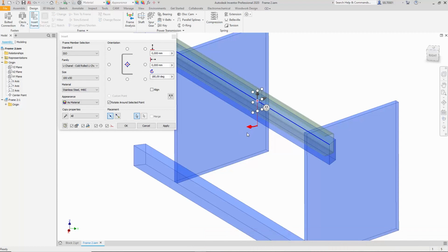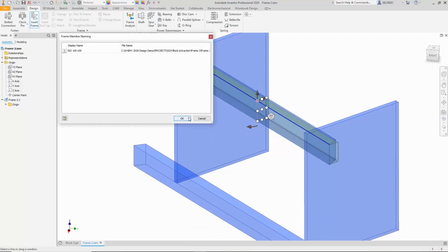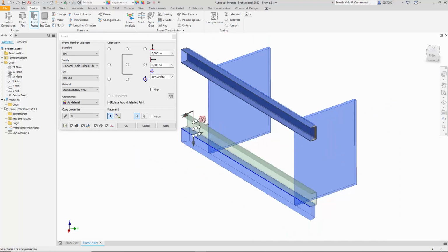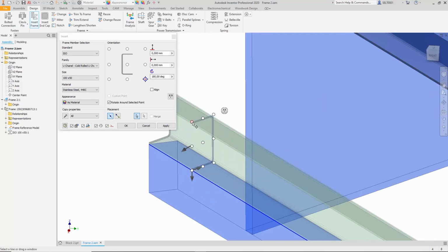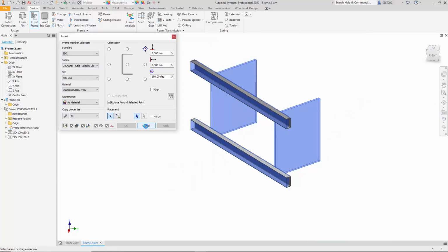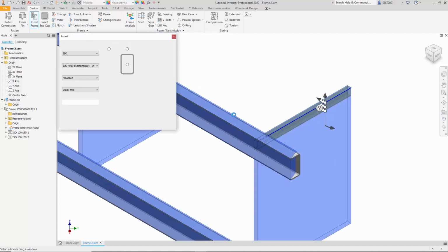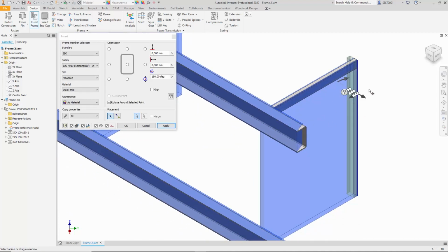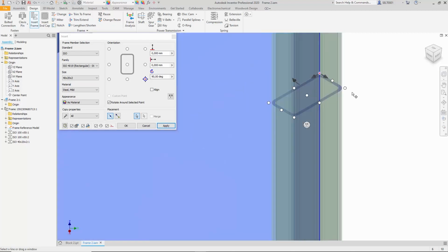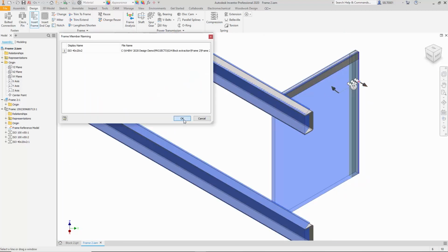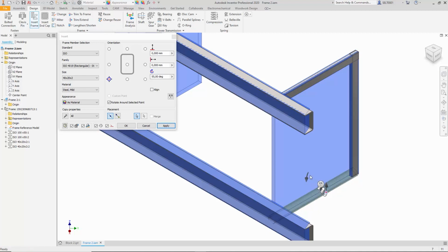Similar actions are performed with a rectangular profile. 40 and 20 measurements are used to make the legs. Adjust and do exactly the same with the edge. The orientation is adjusted, and the base point is selected. In this way, the entire structure is covered edge by edge. Everything is repeated on the other side.